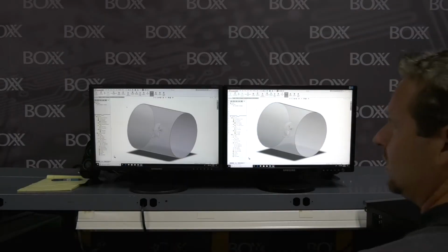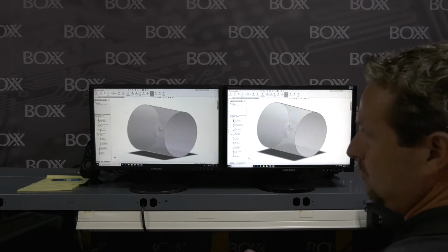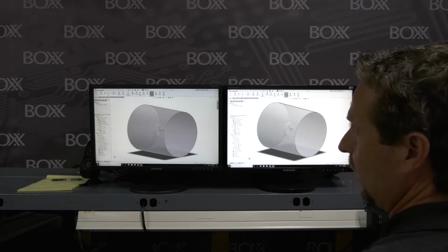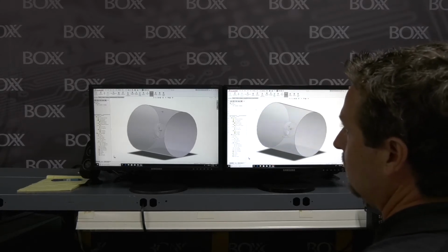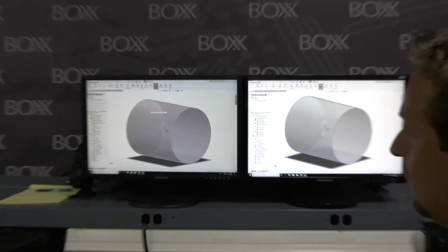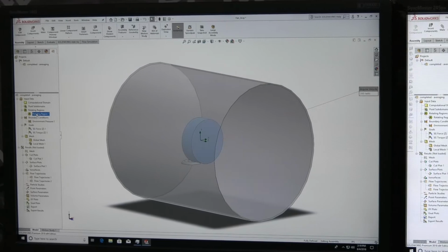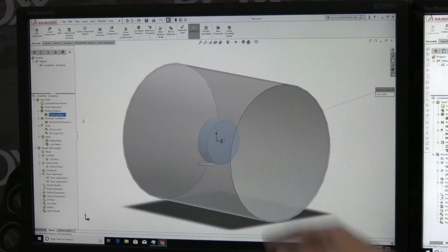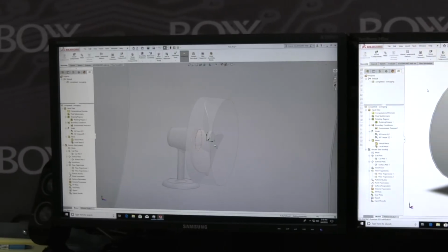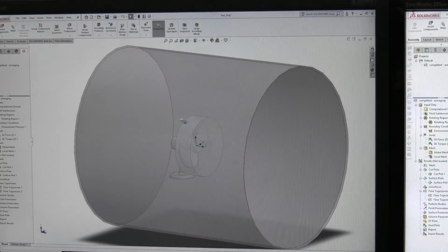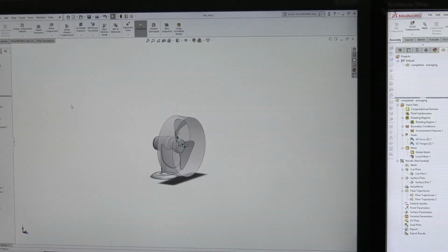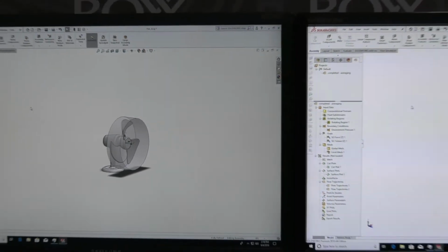All right, so another way to check a little bit more of how the processors help is by doing a flow analysis. So this is CFD inside of SOLIDWORKS. And kind of just for the setup, I've done this as an interior CFD analysis. I do have a rotating region. So kind of this little box is rotating at 200 radians per second. And because I have the little fans in there, the air is going to actually swoop up and start going in a different direction than just kind of rotating, spinning outward. So I'm going to go ahead and turn off the outside computational area there.